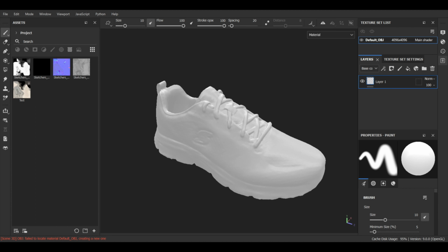And this is why Artec scans typically go through a different process for engineering and become very hard to work with when you are using an Artec scan for something like e-com, which is what we'll be using this 3D shoe for. So the process that you do, and you can pick your software of choice to do this, but you're basically going to take the 2 million polygon file that comes out of Artec, and you're going to reduce the polygon count down to something like 50,000 to 100,000 polygons.